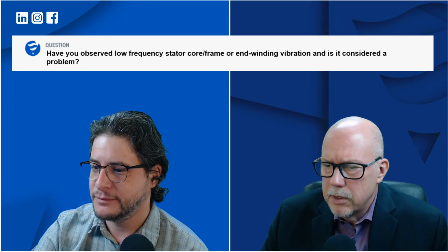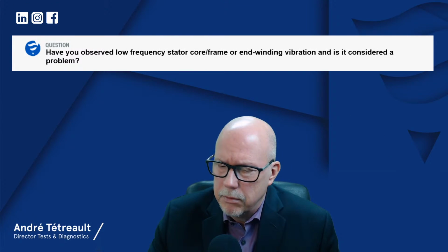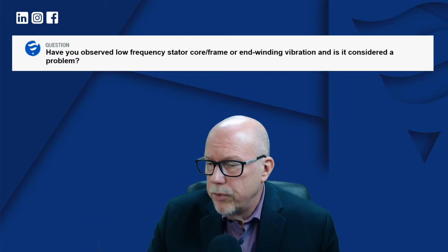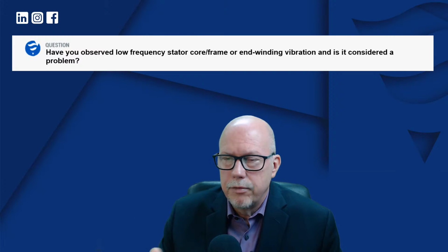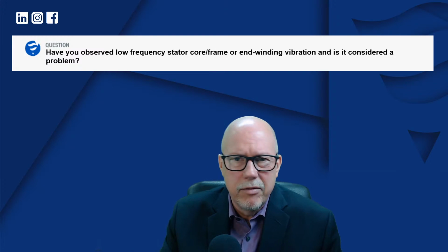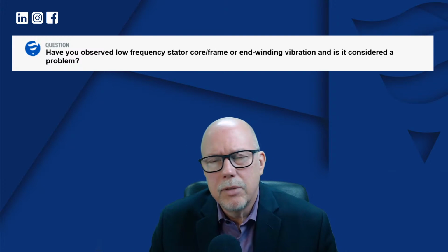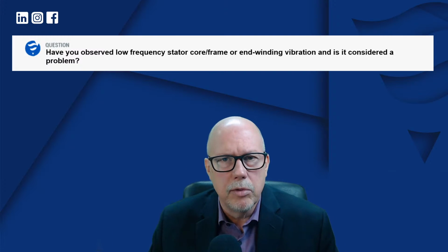Well, it depends what it is. Yes, we have. We've seen low-frequency vibration on end windings. When I say low frequency, instead of seeing, let's say, 100 or 120 hertz and the 50 or 60 mechanical, we've seen like 30 hertz, 25 hertz, 10, and I'm not exactly sure where that's coming from, but usually the amplitude is very low, and most people consider that not a problem.